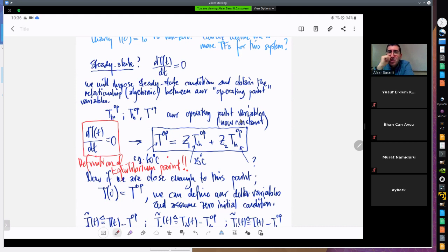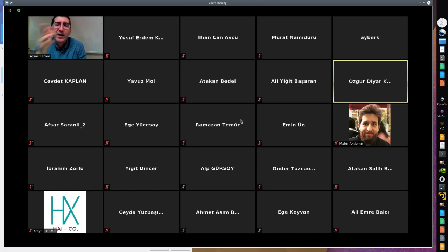Because this equation has more than one variable in it, it is always possible to fix some of the variables and determine another variable that you can easily change. In this case, it's the heater temperature. So in response to a changing outflow operating temperature, let's say instead of 60, you now require 50, you can calculate a new heater operating temperature. You can set the heater around that temperature, and you can use the same model and therefore the same controller. Okay, I got it.